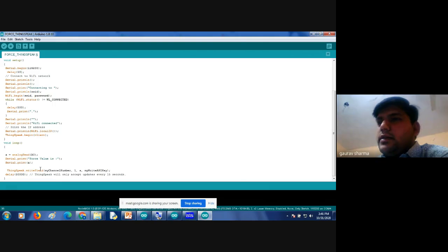You can see there is a link created by this function, ThingSpeak.writeField, with my channel number, field 1, A as the value of the variable, and my write API key, which I already added in the starting part.